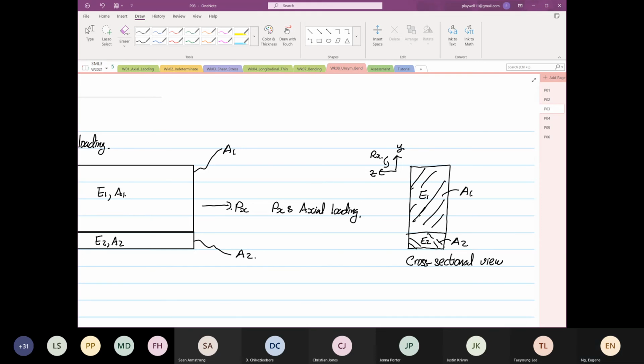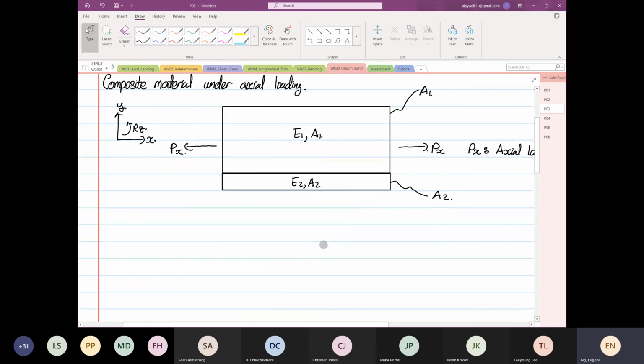For this case, we have to apply Hooke's law. So Hooke's law states that stress is equal to E multiplied by epsilon. Some of you have done your structure and properties of materials. Those of you who have not, what does this mean? So this is strain, this is stress in the elastic region, right? The stress strain curve is straight just in the elastic region. Out of curiosity, this is your yield. So this is your Young's modulus.